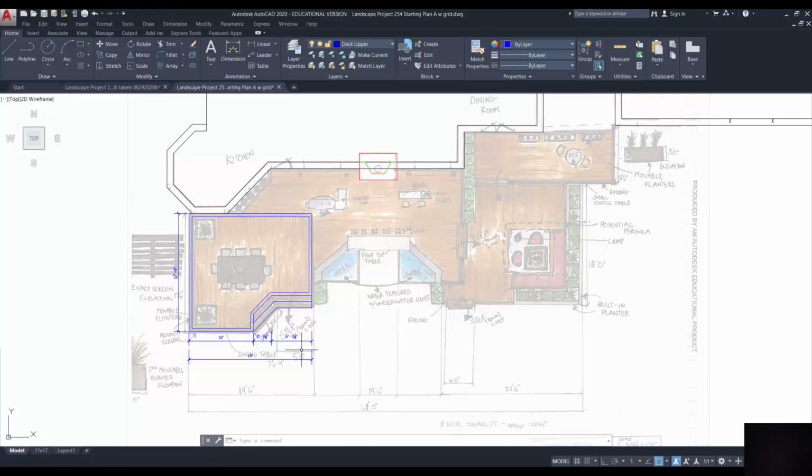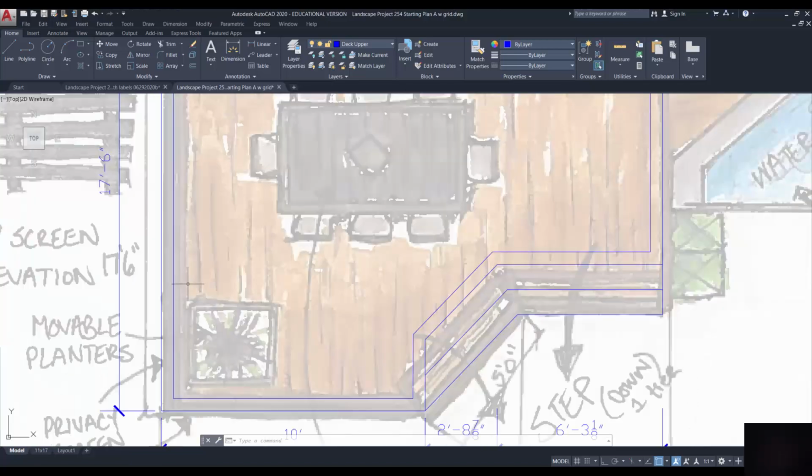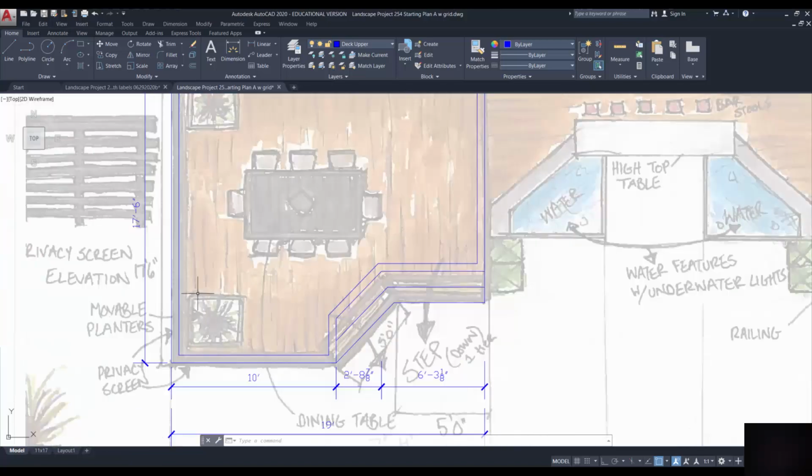The other thing that's still missing here is the actual wood pattern. And there's a couple of ways that you can indicate this. You can simply draw a line through part of this image. It doesn't matter where that line is. And I'll change the color of it, or I'm going to actually remove that line afterwards. And then draw a single line from the corner to the edge of that angled line. And all these are offset by 5.5. That's the size of our boards.